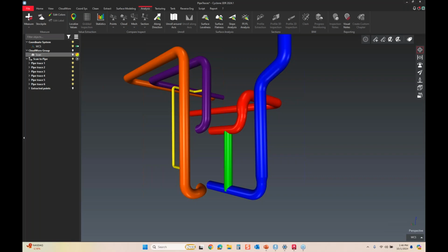And I don't care if they're actually in a survey plane or a known survey coordinate system or not, but if I have some known locations to a BIM model, I would scan with those points and pick them up in the field. And then I can use those points as targets. I don't have to put targets out there, but I can use those as targets to adjust them to the same location and rotation as the BIM model.